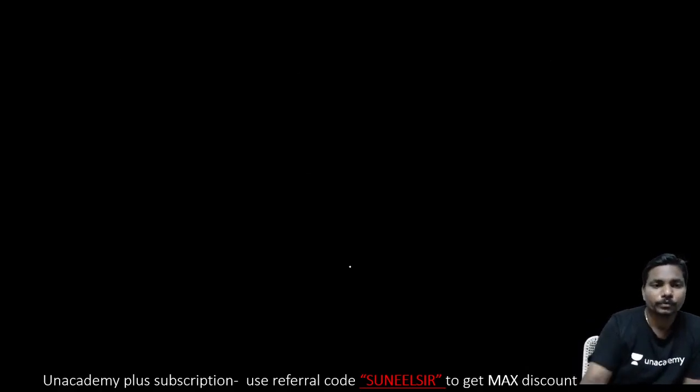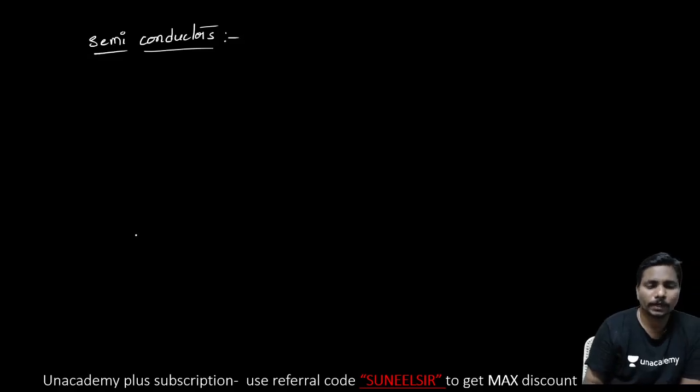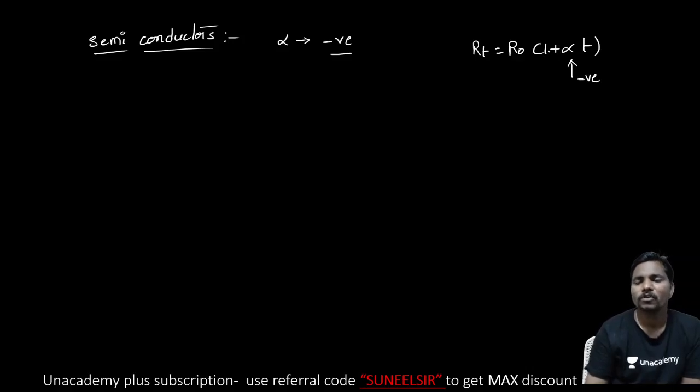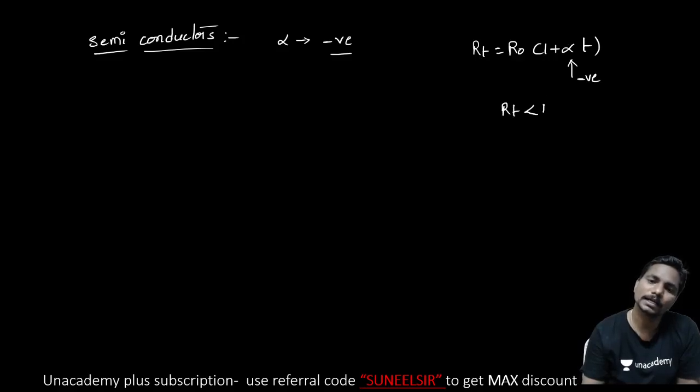Now coming to semiconductors. In case of semiconductors, the alpha value is negative. If the alpha value is negative, then what about RT? RT is equal to R naught into 1 plus alpha T. If this total alpha T value is negative, then you get 1 minus something. 1 minus something means RT is less than R naught.